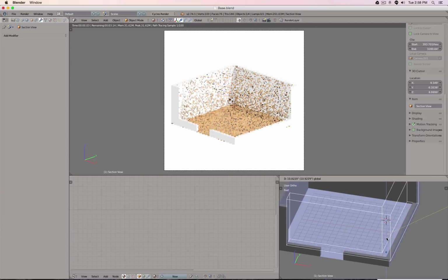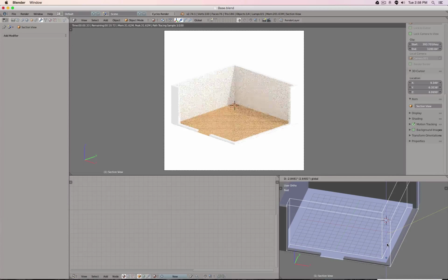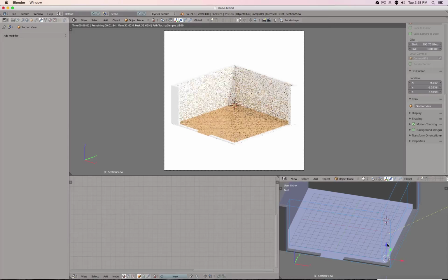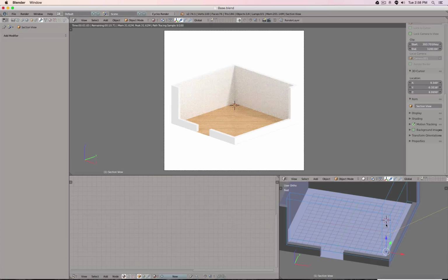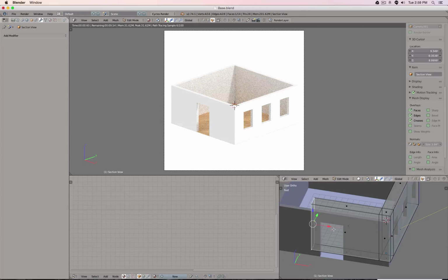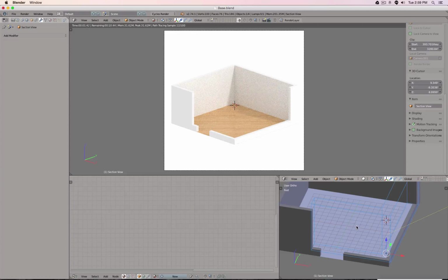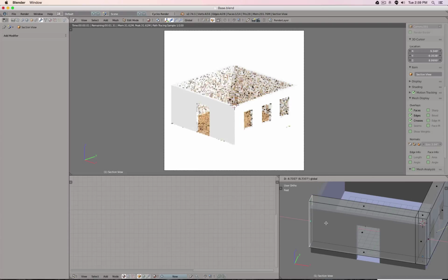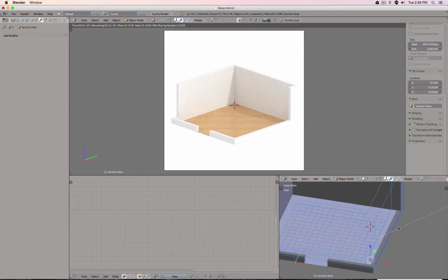So you see how you can adjust now, fine-tune perfectly the layout. So instead of making an adjustment, test render, making an adjustment, test render, I just turn on the render engine and do everything interactively this way. So much better. We can actually also maybe move this one a little bit to there. So with tab and tab, I enter and exit edit mode.